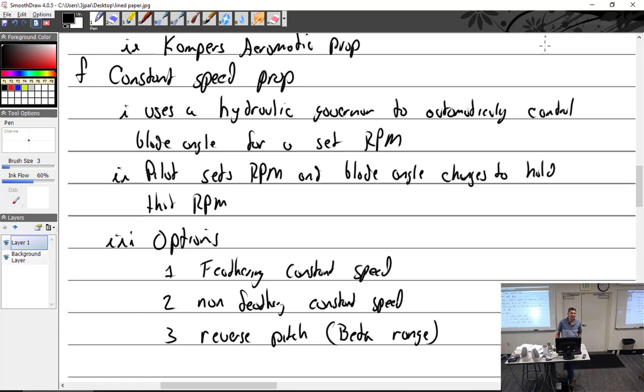So I should say, I think almost all turboprop aircraft have reversing feathering propellers. Even the single engines have reversing feathering propellers. Well, I'm not sure about reversing, but it's definitely an option. King Air has reversing feathering. Well, it's twin, so they reverse. And when you go into flat pitch, where there's no thrust at all, to the negative, that's called beta range.